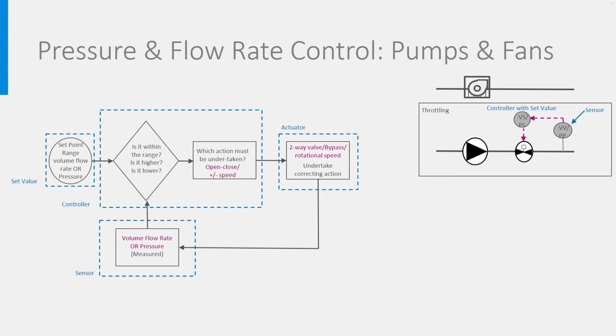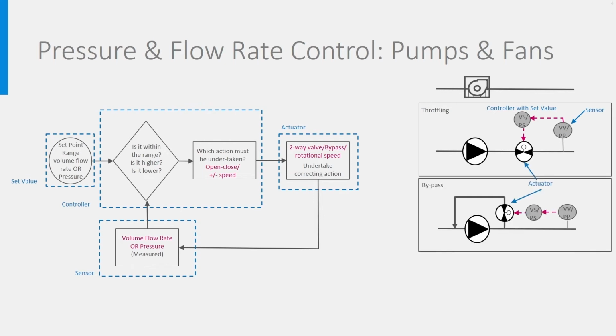The first two cause a lot of energy waste and arise from the times that pumps and fans could only rotate at full speed, so the incoming flow could not be controlled and was always full flow. The first way is to squeeze the flow after the pump using a two-way valve, which is named throttling. When the opening in the duct is reduced, the velocity of the flow decreases before the valve, so the static pressure increases, meaning that the resistance to the flow increases and less volume is pumped, while the pump still runs at full velocity, wasting a lot of energy.